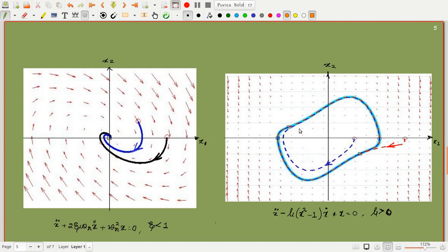But if the oscillation amplitudes are lower, then we can even work with systems with a stable limit cycle, because even if I change the value of x, if I choose a lower value of x, I can reach the limit cycle. And if I choose a very high value of x also, the system will converge and reach that limit cycle.